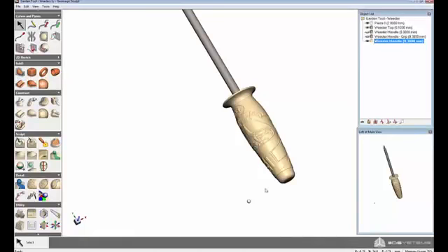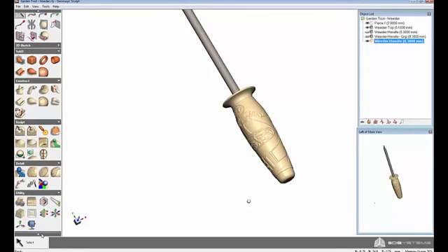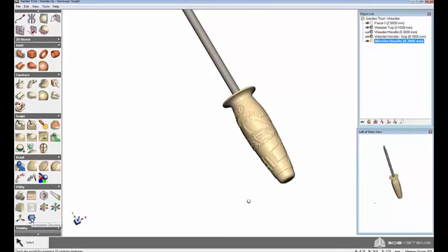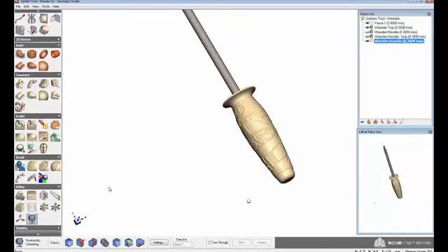All right. Great question that just came in. Does Sculpt have the analyzing capability for accuracy before printing? What we'll do is down here in the utility, we have printability checking. Printability analysis basically allows you to go in and check your part for just that. What will happen before printing? You can come here and see things like, will it fit in my printing volume? What about wall thicknesses? Will things be too thin for me to print? What about even the gaps? Will it gap, or clearances for gaps? So things like that can definitely be checked.